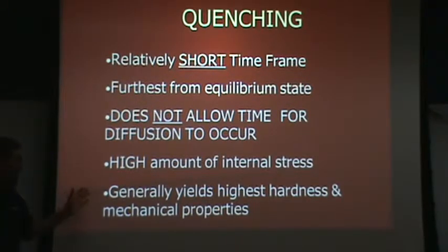I think I showed earlier, maybe I didn't, we'll get to it later, but today we have modeling tools that allow us to predict what kind of stresses we're going to have during quenching. Now, interestingly, for this particular customer example I just gave you, we did do the modeling, and there was no suggestion from the model that we were going to have a cracking problem. And yet, there's a bunch of these parts that are cracked, and we know that the cracks occur during our quenching. So the models are not 100% effective. As with anything related to computers, they're only as good as the inputs, and you're always working to make those inputs better.